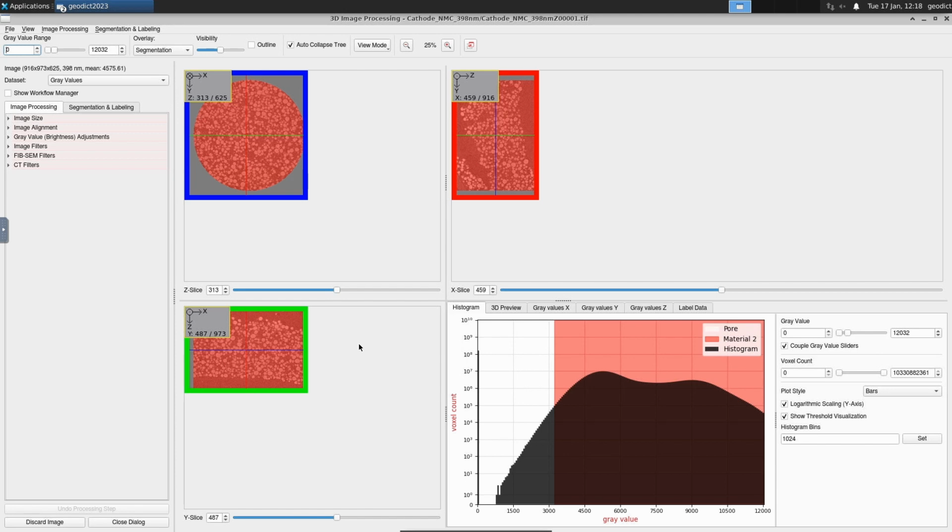One of the first things you will notice is that everything looks very red here, which is a bit weird. This is because by default you get an overlay shown here of the segmentation, and since there's a lot of black area around the structure, the automatic segmentation only segments the outer area from the inner area, and the whole rest of the structure is shown in red, which marks that this is segmented as a structure.